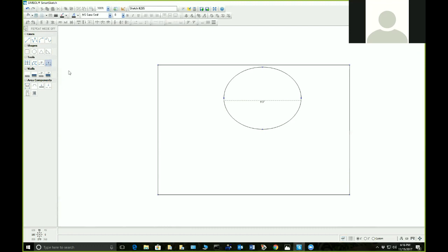Another one that's kind of neat is right here, and it's called the label line tool. What this tells me I can do is draw a line, which is right here. I select it, and then I can put whatever text that I want. So if I need exterior wall at 26.6, I can place that in there. So whatever label that you'd like to put on that line, you may do so. Okay, and that is called the label line.